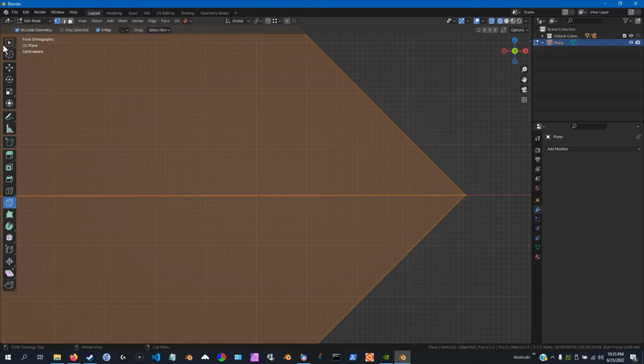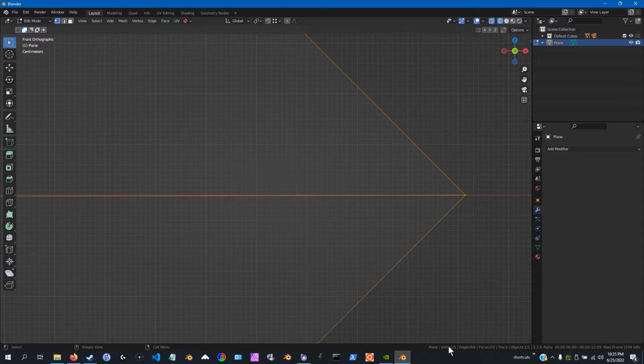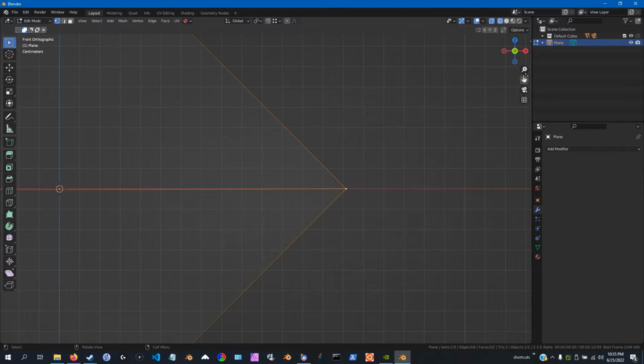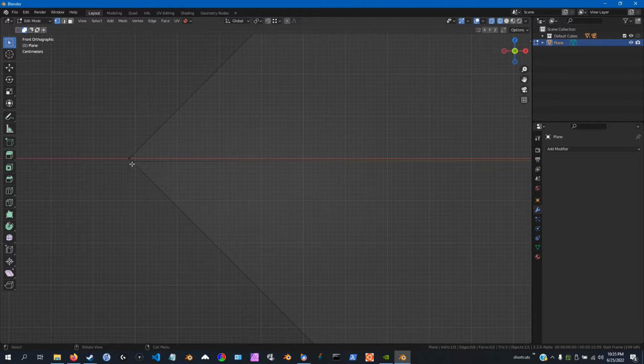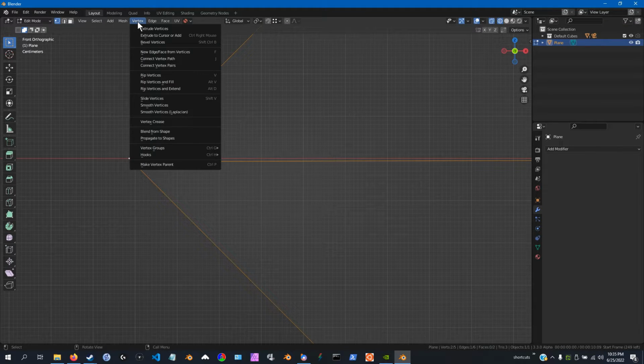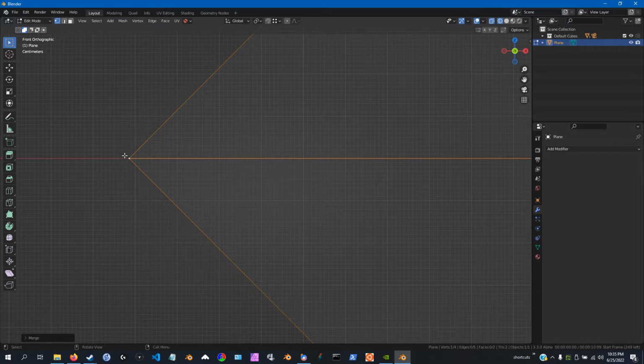If I select this box and then look down at the bottom of Blender, it'll tell me I have one vert selected out of 5. Now it's a square, so there should only be 4 verts, and we can see the problem. I need to connect those 2 verts and make them just one. So I selected one vert, then the other. I want to merge the first one to the last one. So the original position of that first vert is maintained.